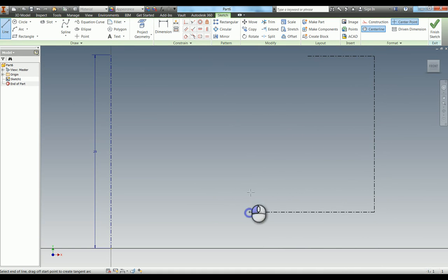And you can actually see that by accident I've left the centerline command on, and that's not actually a problem, because like everything else in Inventor, afterwards I can always edit it. So I'm going to select all of those lines there. If I drag a box from right to left, you can see it goes green. Anything that I touch with that box will be selected.